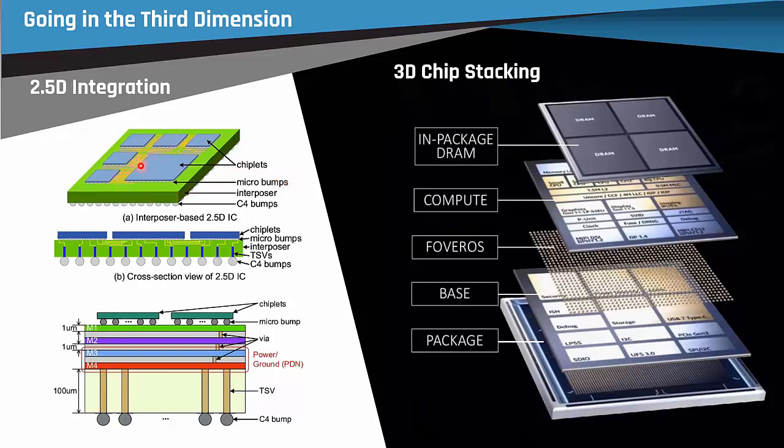So what you can see is we have this substrate, which is what connects to the package, and you have the wiring that actually goes through the silicon to the different dies. That's been used for several years now, but it's getting really popular. I guess it's getting a little bit cheaper. It makes the whole system integration much more complex, but the yield goes way up. And in the end, if you do it right, you can get a cheaper and better product.